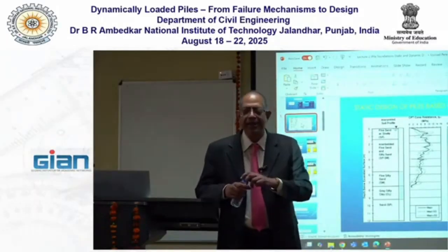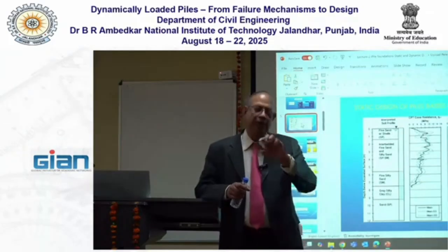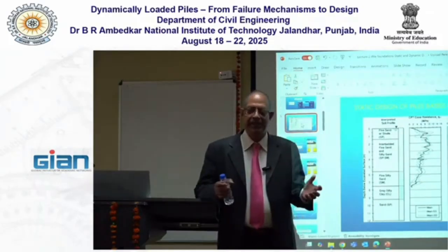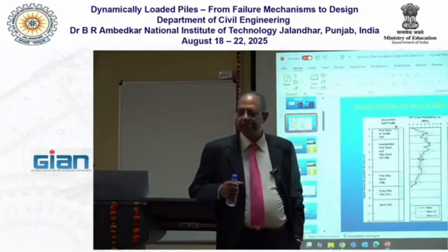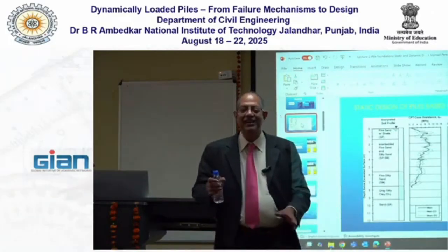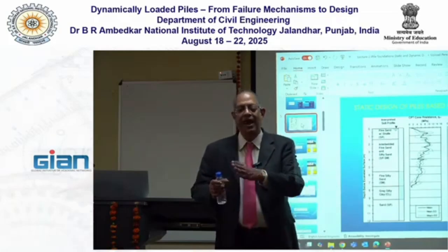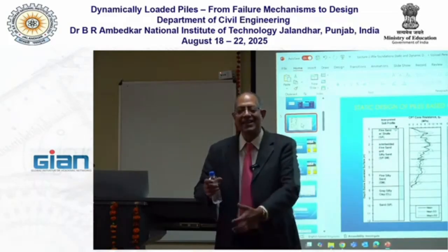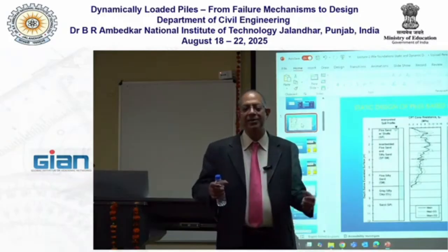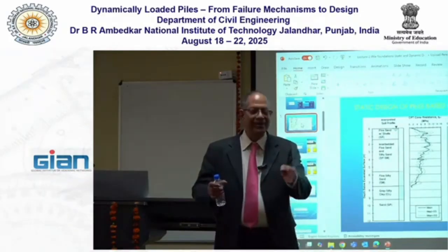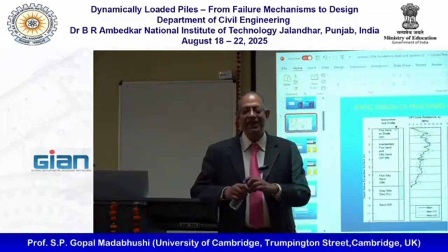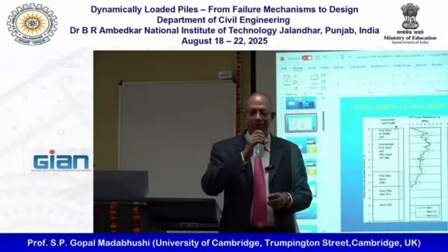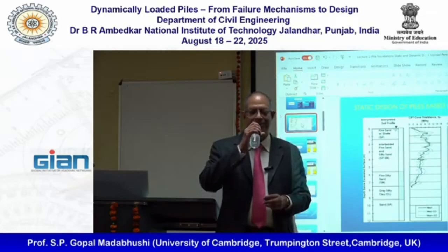I think Dave White or somebody came up with a paper saying how you do a shallow layer correction for CPT and T-bar values, especially for soft clays offshore Perth, right? Yes, you can do that. I'm just trying to teach that you should try to use the CPT direct correlation. I like that because you're doing exactly the same thing to the soil, whether you're driving in a pile or a CPT. So surely we should be able to scale from CPT to pile much better than trying to work these bearing capacity factors randomly. For offshore, you certainly should use CPT, no question.